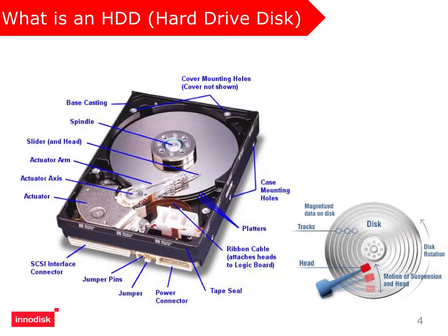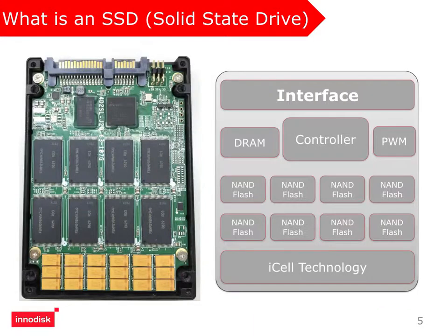The platter and the head of the actuator are covered with magnetic material. When the two are close, it changes the polarity of the platter, so the information is written in. However, when the actuator's head touches the platter directly, it will result in data loss, making the hard drive vulnerable to shock and vibration. A very important point is that new data can be written over the old data without any erasing necessary. Now we take a look at how the SSD works.